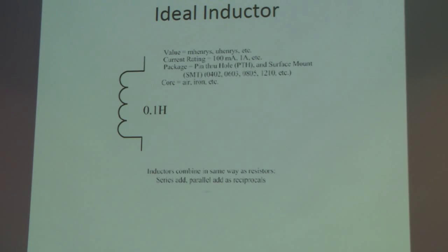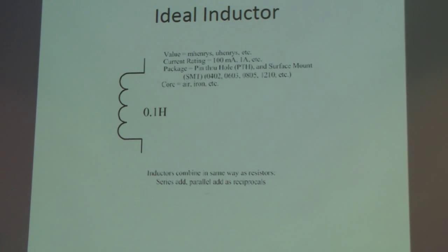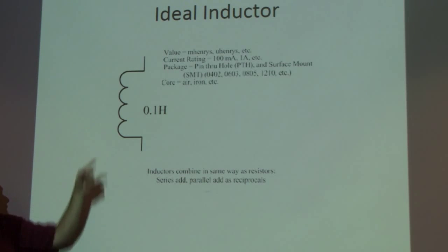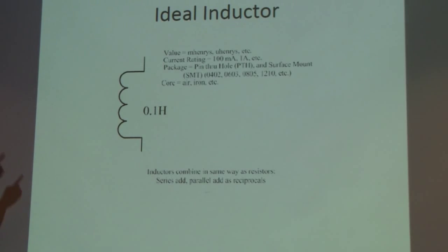Where this comes into play is if you're using an inductor, for example, at the output of a switching power supply. That's one of the things people get trapped by: they may be building a power supply capable of 5 amp delivery, but the inductor is only a 1 amp inductor, so it throttles the power supply. So the key takeaway from this slide is that inductors are a function of current. The entire effect is based on current, and they are ultimately limited or described by how much current they can deliver.